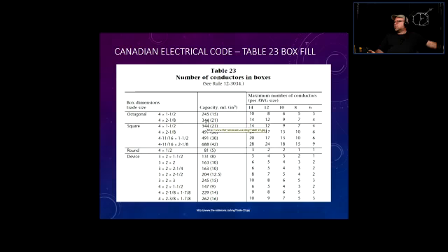So of course it will have more volume, 344 milliliters, or 21 cubic inches, and we can fit more wires because the box is bigger. So with 14 gauge wires, we can fit 14 conductors, then 12, number 10, 9 wires, 8, 7, and gauge 6, only 4 wires.